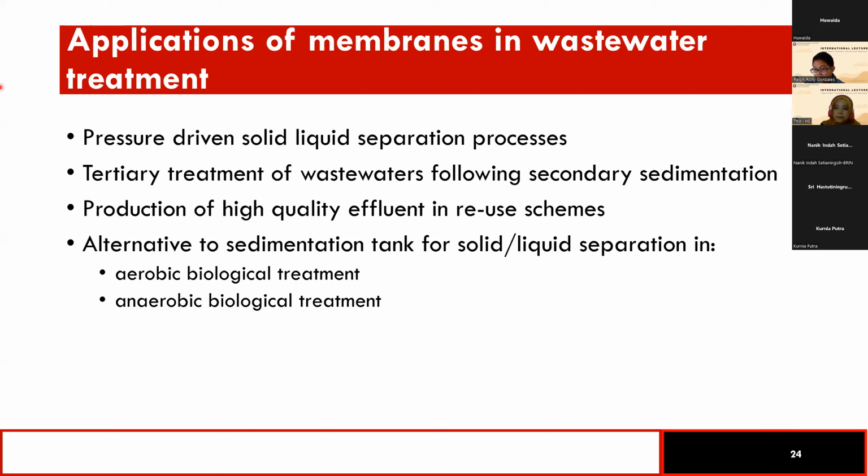And lastly, membrane technology can be used as an alternative for the sedimentation tank for solid and liquid separation in these processes. So as I earlier mentioned, most wastewater treatment plants use sedimentation tanks, which allow the deposition of solid wastes and allow the water to just pass through.